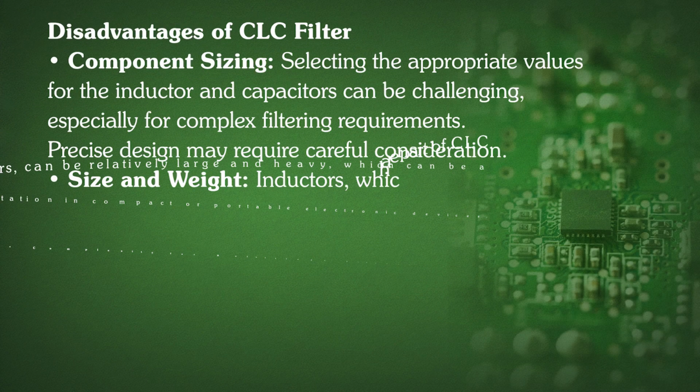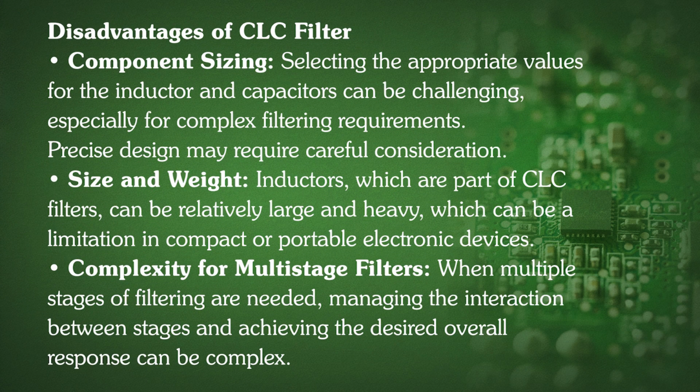First disadvantage is component sizing. Selecting the appropriate values for the inductor and capacitors can be challenging, especially for complex filtering requirements. So, precise design may require careful consideration. Next disadvantage is size and weight. So, inductors which are part of CLC filters can be relatively large and heavy, which can be a limitation in compact or portable electronic devices.